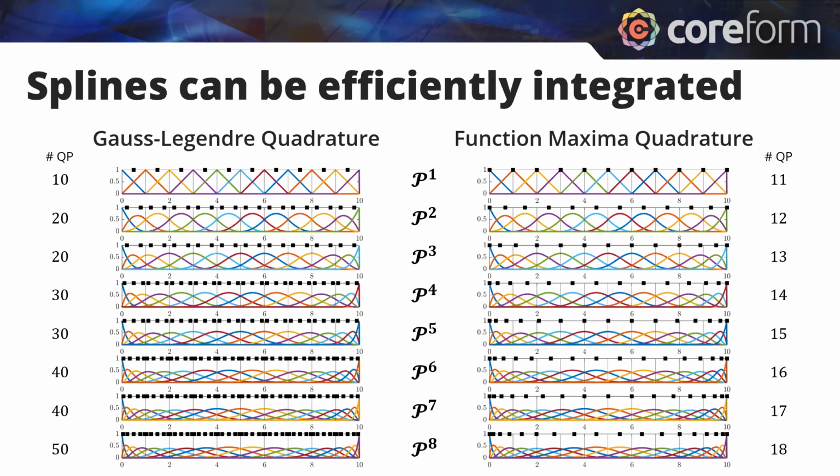That stiffness matrix would be on the order of 81 by 81. There are obviously material models that will make it bigger, but that's really the scaling. Yes, it will be sparser than the smooth splines, but it's also 81 by 81, whereas here we're dealing with an 18 by 18.